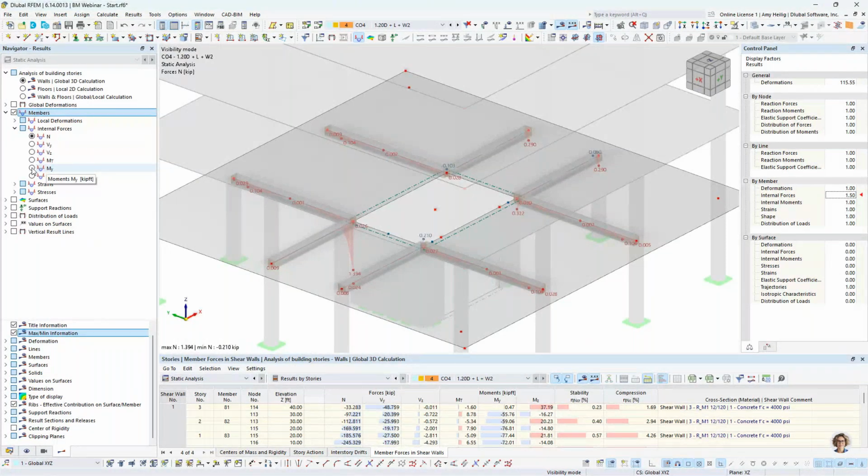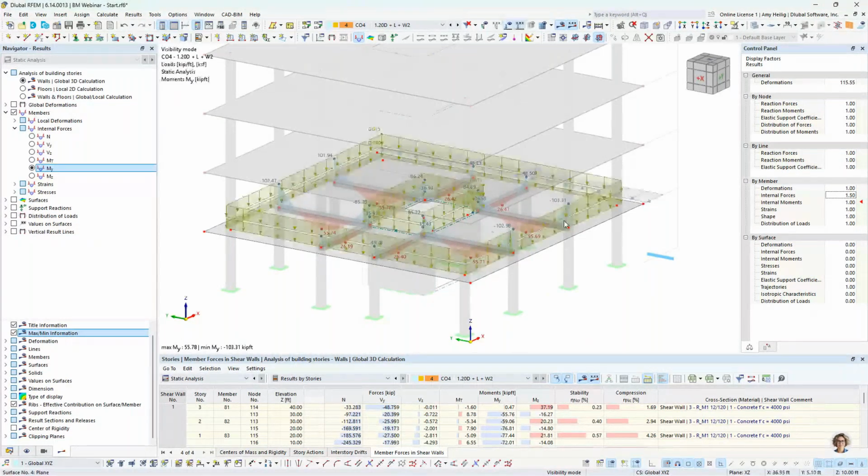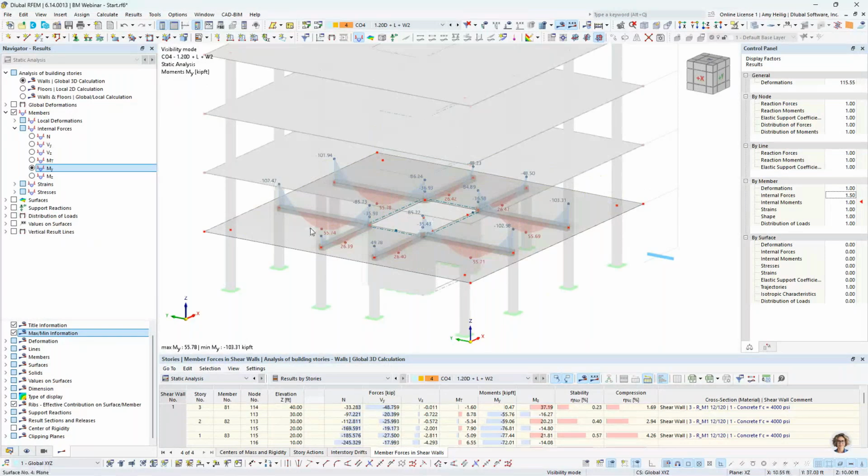Now, we also can view bending moments because this isn't just lateral loads being applied to the members in the 3D model. We're also applying those gravity loads that we talked about too. We can see them applied here within the model. So we will have these beams designed for the gravity loads as well as the lateral loads.